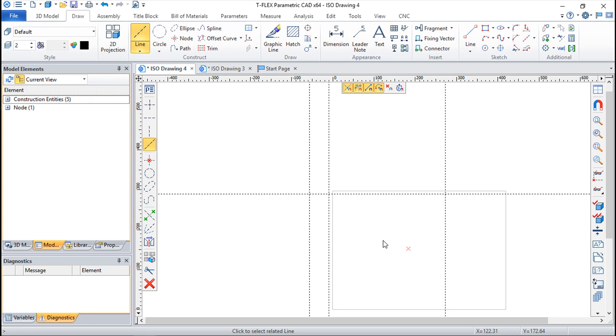So imagine the situation where you are making an assembly, and this assembly has elements that are represented in 2D. So you are creating lines, and these elements, if they are behind the part, should not be visible. So you can have your elements there, and the priority will put them behind this other part that in fact is just a set of lines.